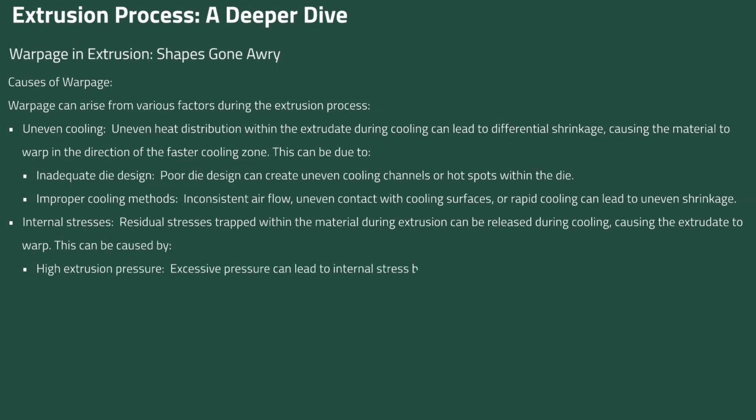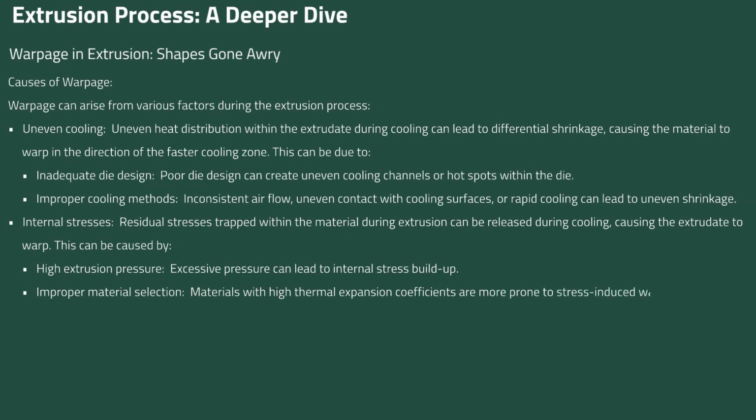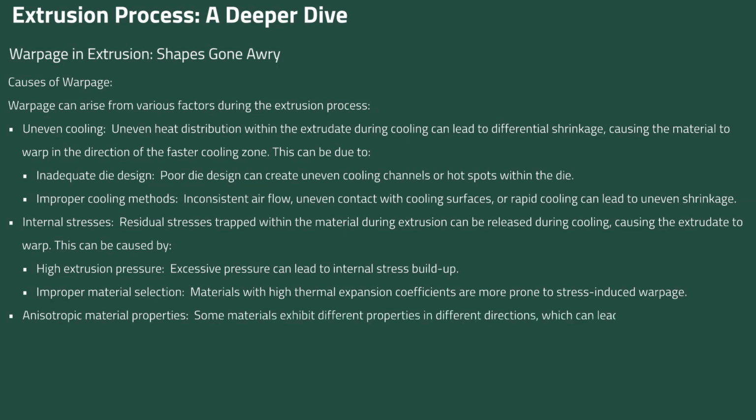Excessive pressure can lead to internal stress buildup. Improper material selection: materials with high thermal expansion coefficients are more prone to stress-induced warpage. Anisotropic material properties: some materials exhibit different properties in different directions, which can lead to uneven shrinkage and warpage during cooling.